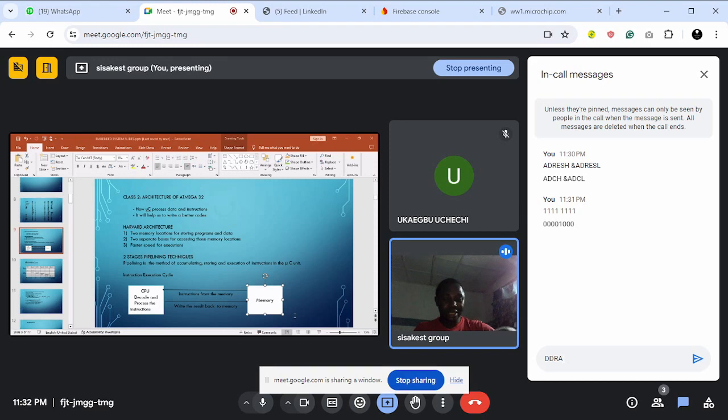This is the port A register in ATMEGA. You understand? DDRA is in ATMEGA, and in PIC it is different. So we'll be looking at those things. So what the CPU does is it decodes information. It decides whether to write 1 0 0 0 0. That means you turn on a particular output as a result of what you saw there. You understand? Or you turn off a particular output.